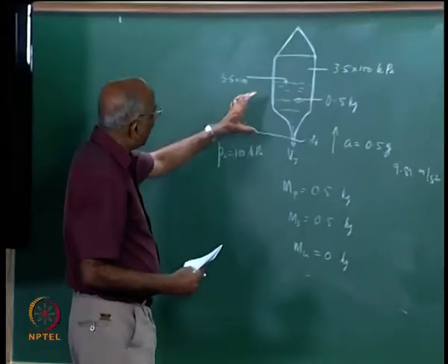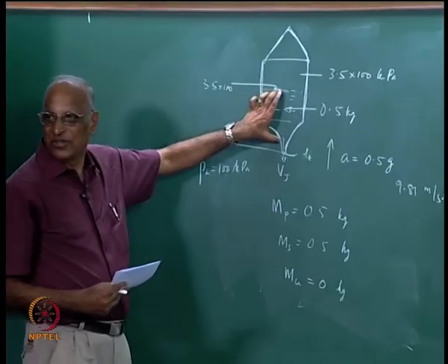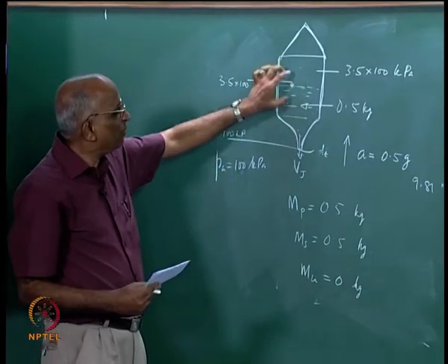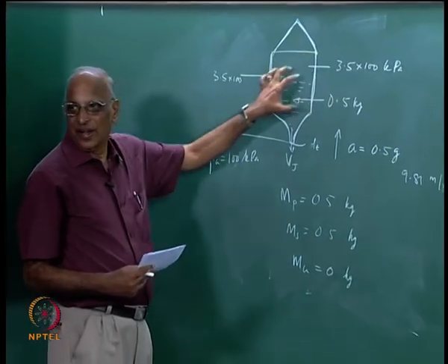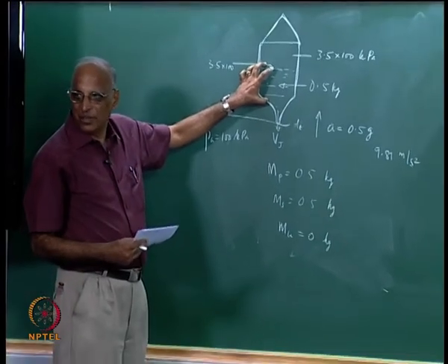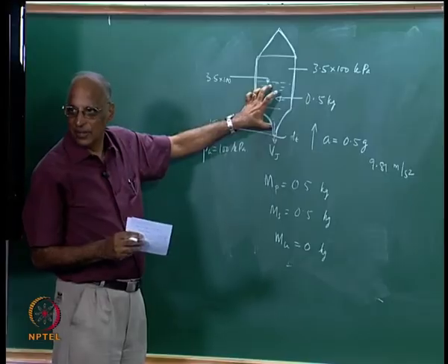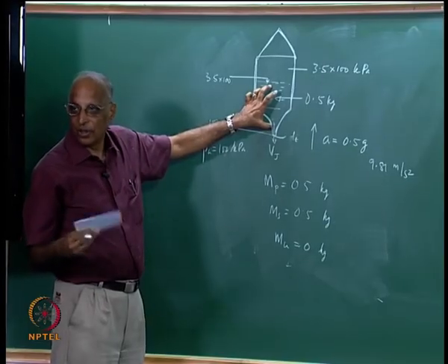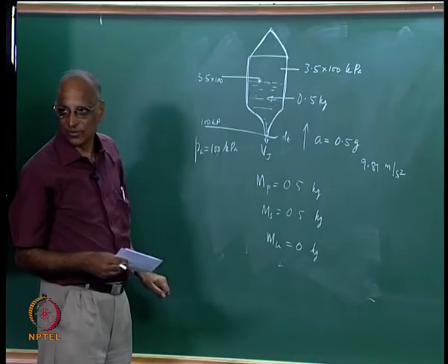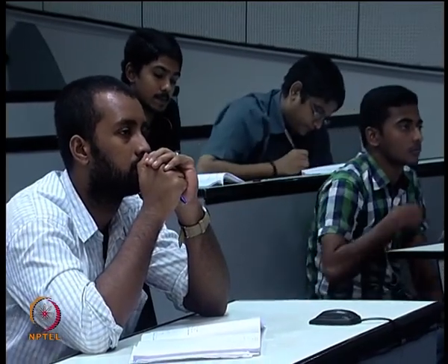See, I said let us neglect the height because the height is small, because you have the pressure which is so high that the height will really not matter. But in a real problem, yes, I would like the weight of water due to the height also to be considered. Now, we just wrote the Bernoulli equation and tried to do it.